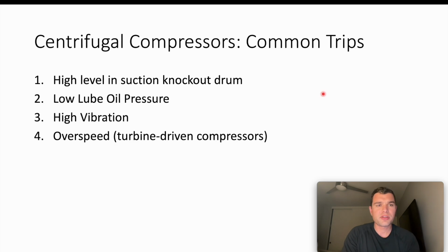As a summary, the four trips that we went over are high level in the suction knockout drum, low lube oil pressure, high vibration, and overspeed for turbine driven compressors. A reasonable question is, why is this important? I'll answer that with an example.